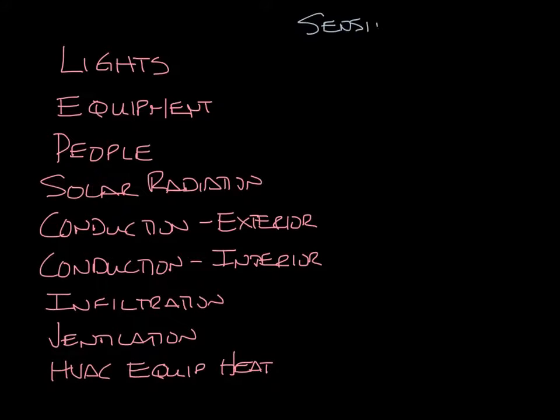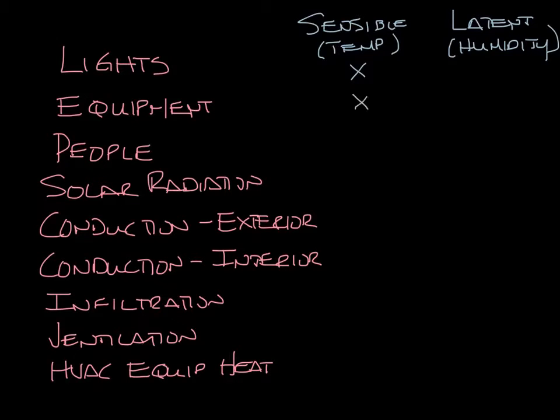You also need to know if the loads are sensible, which raises the temperature of the air, or latent heat loads, which raises the water content of the air. Think of it as humidity. The lights don't raise the water content of the air, so they're just sensible loads. The equipment could do both, like maybe a coffee maker would put humidity into the air.